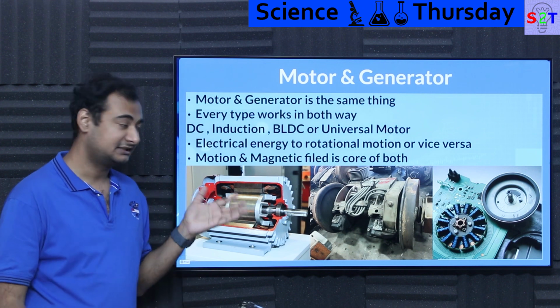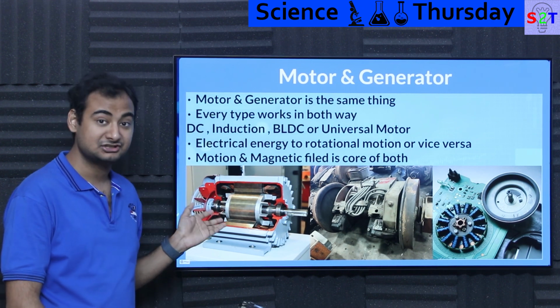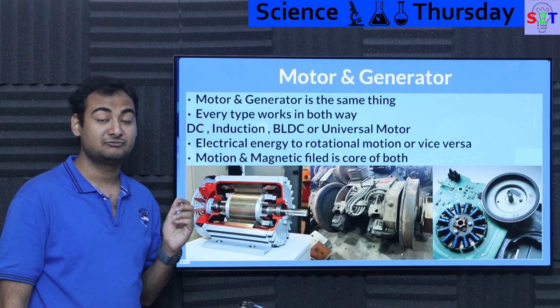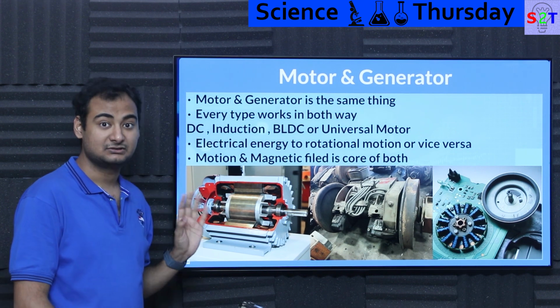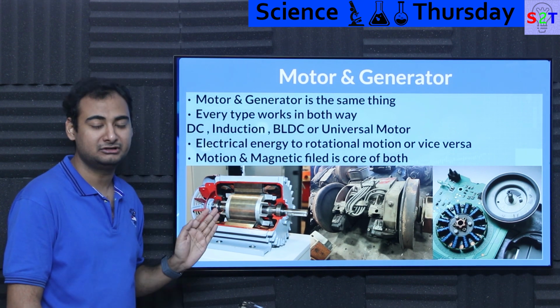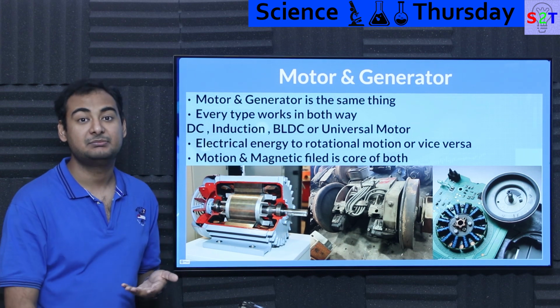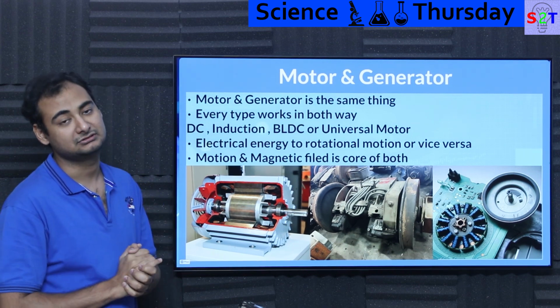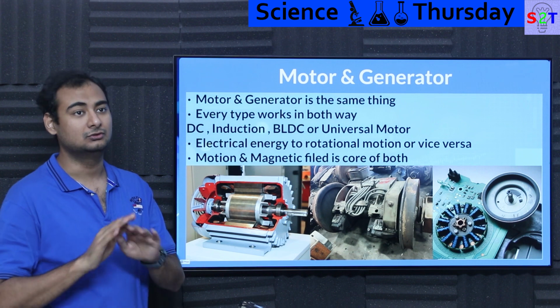And yes, there are companies that make induction motors basically as generators. Some wind turbines also use that. So yes, a normal induction motor, you do not have to make any modification. Everything outside of it is basically the drive circuit, meaning all you have to do is add some capacitors. Done, go home, sweet dreams.